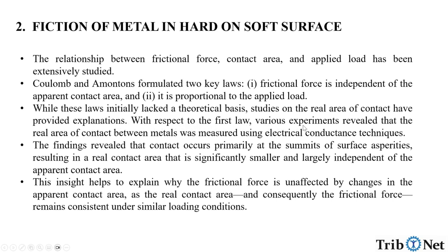to the first law. Various experiments revealed that the real area of contact between metals was measured using electrical conductance techniques. The findings revealed that contact occurs primarily at the summits of the surface asperities, resulting in a real contact area that is significantly smaller and largely independent of the apparent contact area. This insight helps to explain why the frictional force is unaffected by changes in the apparent contact area, as the real contact area and consequently the frictional force remain consistent under similar loading conditions.